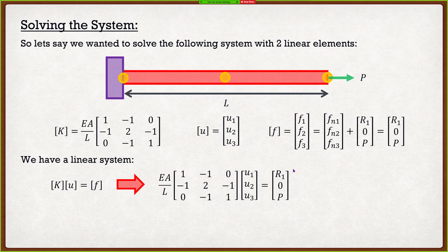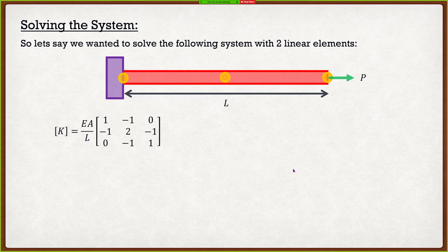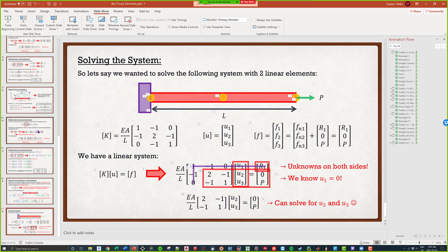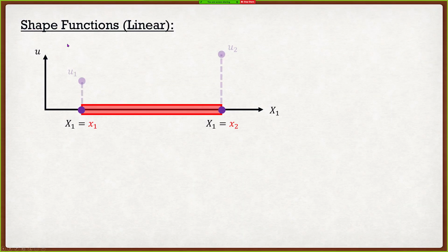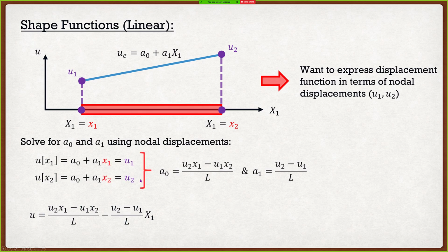Now, even though I don't have a slide talking about it, you already know that if we have those nodal displacements, we know the displacements of the elements, because our elements are simply displacement functions. For instance, if I go all the way back, where would be a good slide? Probably this one right here. Remember that we had the displacement of a linear element as simply a function of U1 and U2. Since I now know what U1 and U2 are, I have my displacement approximated over the elements.